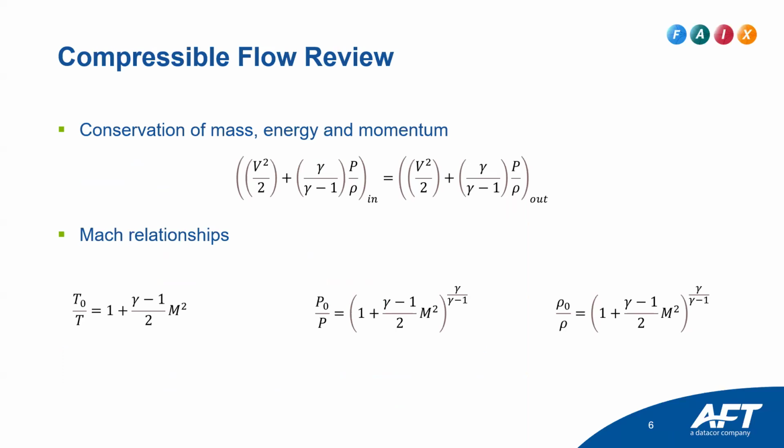So here's a very brief and simplified review of compressible flow. Compressible flow theory network solutions are based on the laws of conservation of mass, energy, and momentum. This right here is the general energy equation you're probably familiar with for compressible flow. And this is a simple form that neglects effects of elevation changes, friction, heat transfer, any dynamic mixing between your gases, real gas effects, and so on. But these things are captured by AERO.